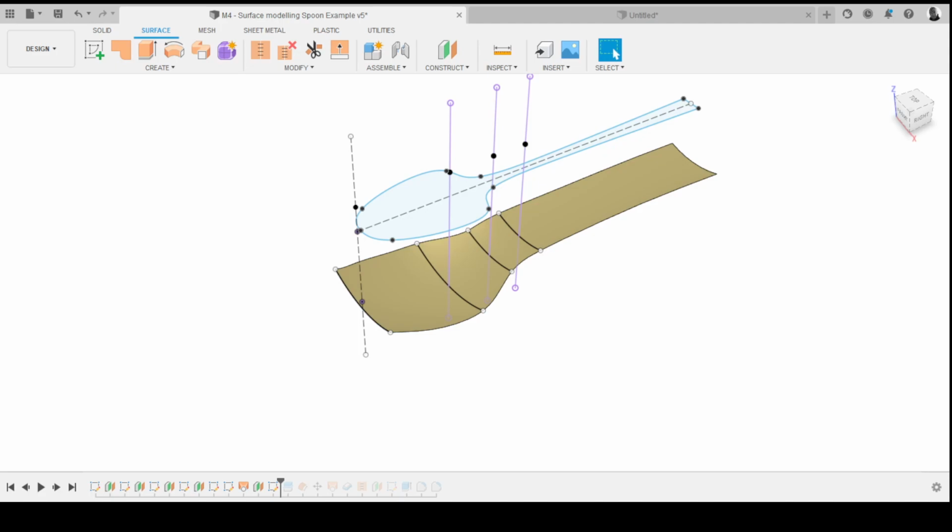If you wanted to have a spoon with a cylindrical handle, would you just, when you did your original sketches before you created the surface plane, would you stop it short, so you'd have the head of the spoon, and then once you've done all this bit and created a solid body, add an extra thing and then do a solid loft to connect the two so that you had a smooth transition from flat to cylindrical?